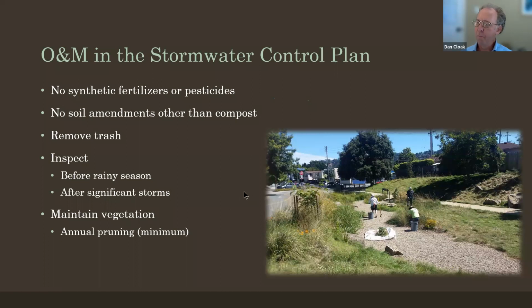I've seen bioretention facilities that perform great, and the vegetation maintenance on them is to go in there in February and cut everything back. The neighbors might complain that it looks like hell for a few weeks until things warm up and start growing again. But in terms of keeping minimum costs, particularly for publicly owned facilities, that is often completely adequate.